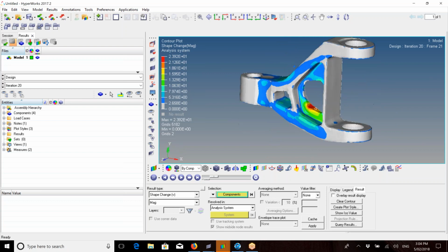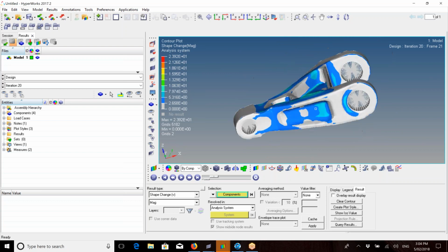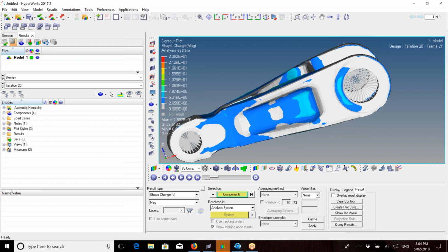So another thing as well, there's around the holes where the constraints and loads are, those holes haven't changed because remember how we deselected the nodes? So it's very important, if those nodes weren't deselected, we would actually probably see some warping in there, like some hole size change, where if that's going to be like a proper constraint, say on the bolts and stuff, you don't want that to change. But if you've got full design changeability on those sections, it's always worthwhile leaving them in there and seeing how they perform as well.